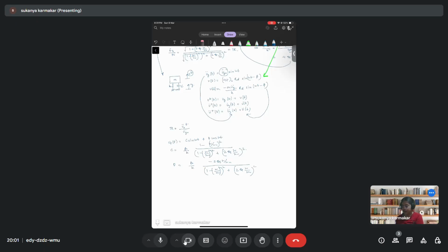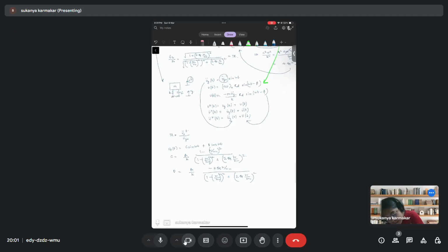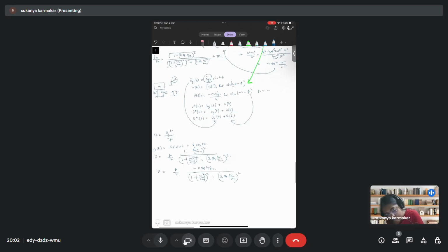Now here, since this is a ground excitation, your P naught is equal to minus m ug double dot. This we had understood through force equilibrium, when we subjected a body to ground excitation, and we had derived that your effective force becomes minus m times ug double dot.